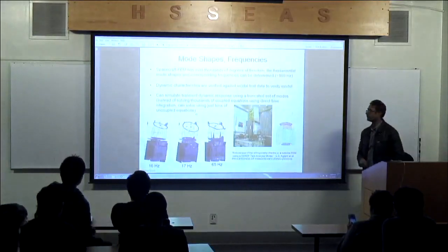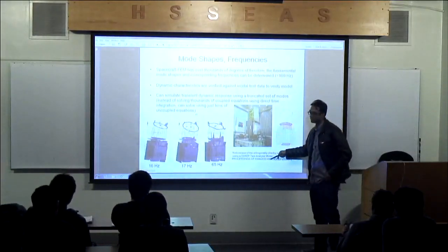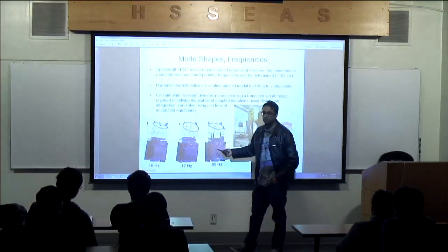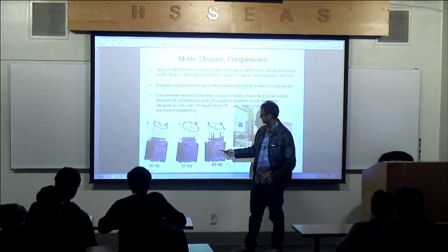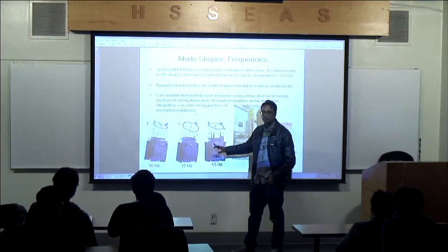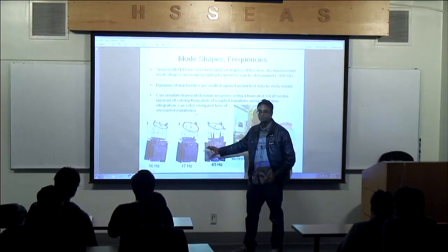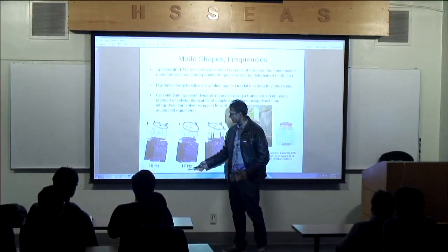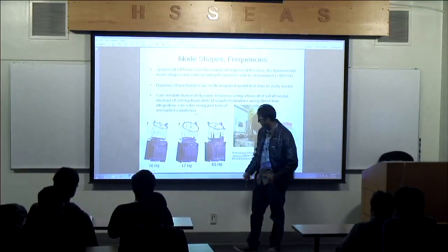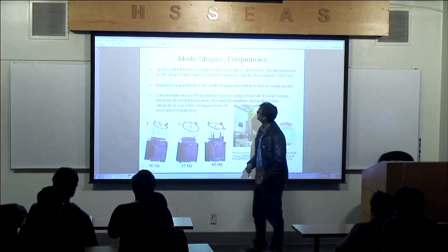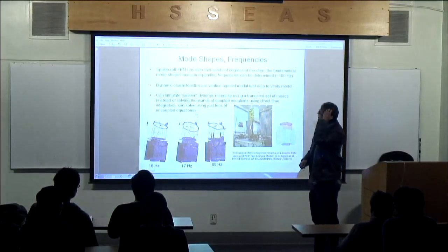So let's talk about a spacecraft here. That's a spacecraft. Here is a reference for that picture. This is a finite element spacecraft that has, I couldn't tell from the images, but you can see very small elements there. This looks like millions of degrees of freedom, but just to give it the benefit of the doubt, let's say it's a million. Some of the frequencies were 16 hertz, 17 hertz, 65 hertz. Some of the motions were different, like torsion. There's bending, you can see that's bending right there. The spacecraft here has thousands of degrees of freedom.